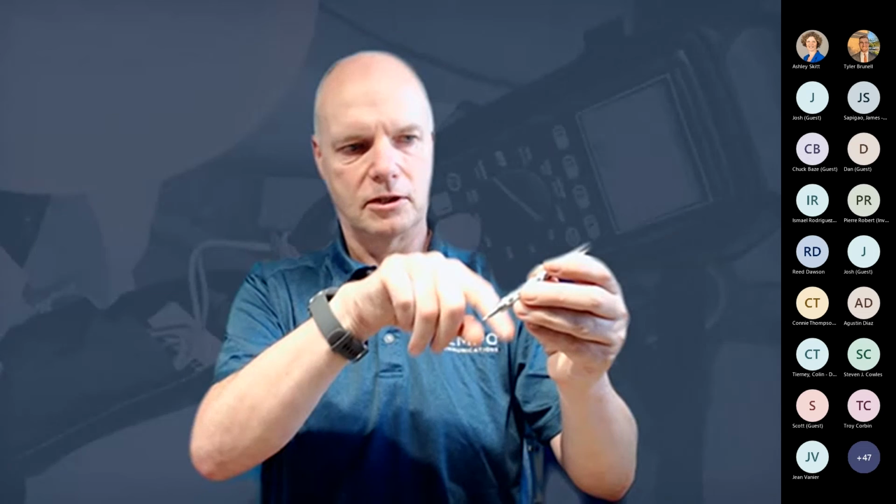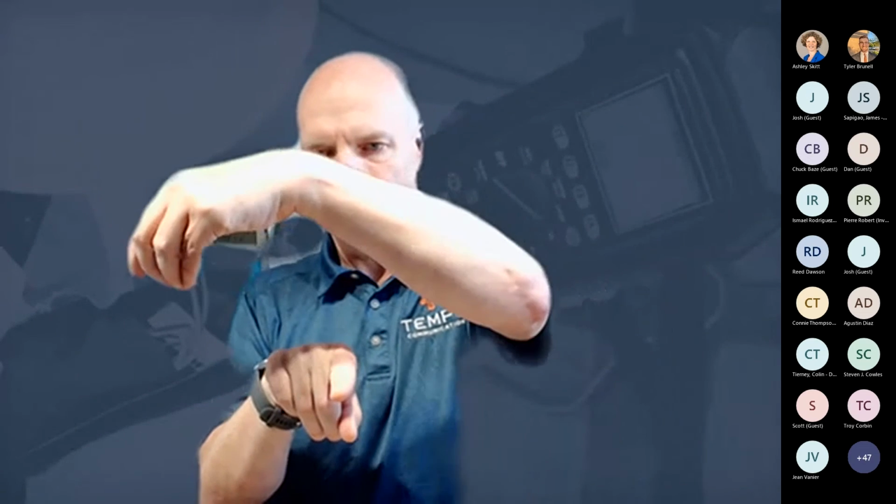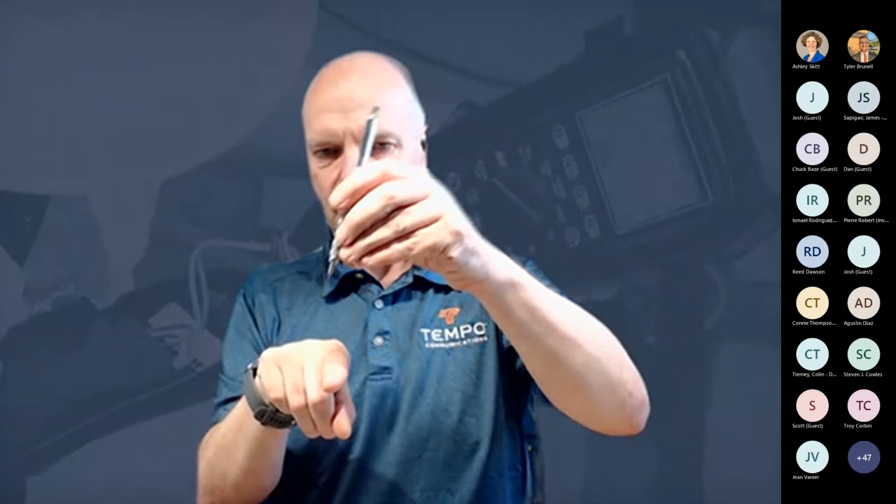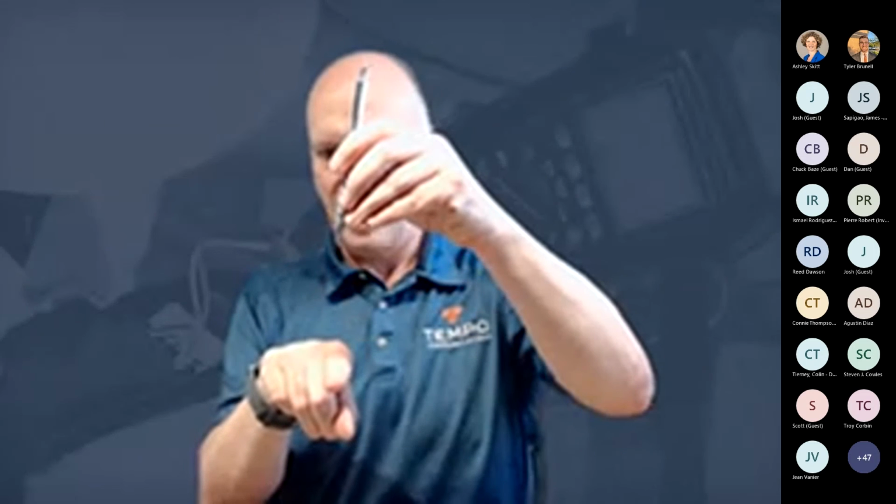When it gets over to here, that is again at 90 degrees to all the field lines around this cable. You would repeat the same on the opposite side, and make sure the measurements you made on either side are the same. Because this is at 45 degrees, a right angle triangle is formed between the depth and this distance across. So we just have that lovely geometric depth with the 45-degree probing.